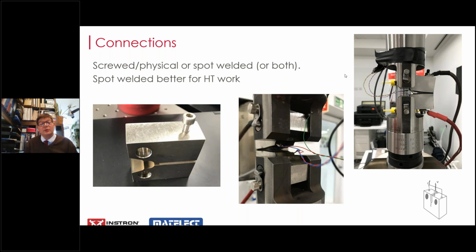At some point, we will want to take the data generated from the voltage and generate a value which is proportional to crack length. This means that if we are to have repeatability across tests, these connections to the specimen must be made in a known manner. Throughout the literature, there is also a clearly defined set of equations which can be used to convert this.